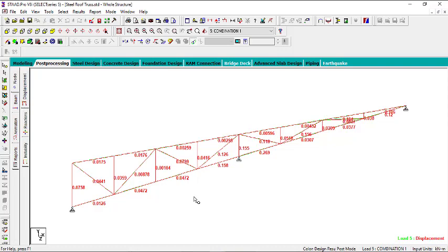For a proper and accurate design, you cannot have an utilization ratio greater than 100%, and that is 1 unit. So if you look at all the members we have here, look at this. This is not even up to 0.1. This is 0.0758. Also, this not up to 0.1. Almost everything here is not up to 0.1. Okay, we just have few that are up to 0.1. This is a very good result. Alright, so you can do all this while you are designing.